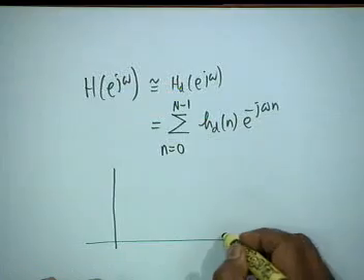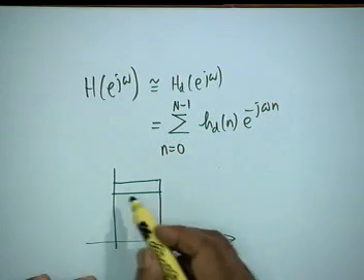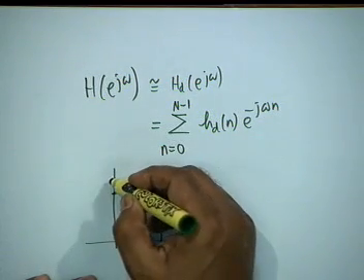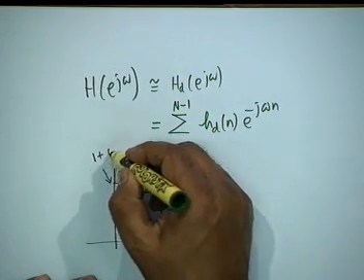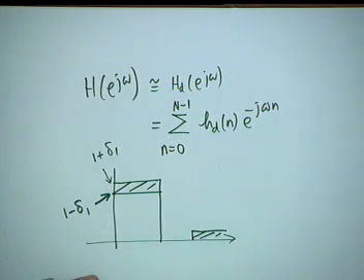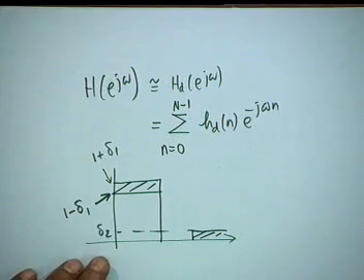not with the kind of tolerance scheme that we are following. What do we follow? Highest is 1, in the pass band lowest is delta P, and in the stop band highest is delta S. For historical reasons, I do not know why, they used it differently. These empirical formulas are given for a typical low pass filter with the maximum as 1 plus delta 1, the minimum as 1 minus delta 1, and the stop band ripple as delta 2.